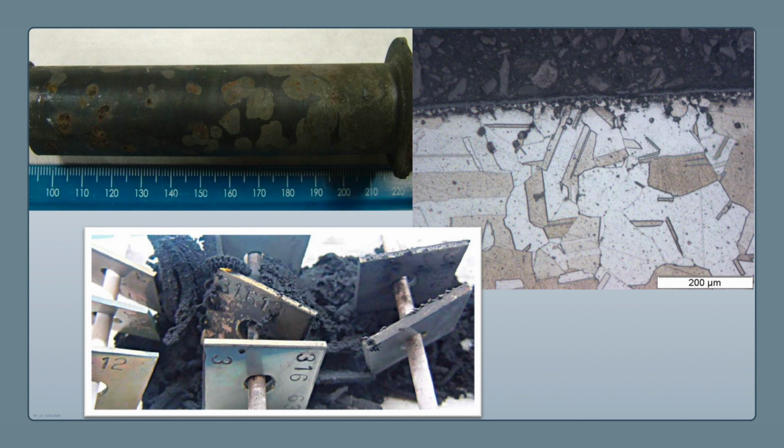In the bottom picture, we've done quite extensive work to try and simulate this type of failure or corrosion in the lab. Some of my colleagues have developed this furnace. We look at the environments and mix the gases and put them through the furnace, looking at different temperatures and time periods. These are also just 316 stainless steel coupons where you can see the dust that's come off. The coupons themselves still look fairly clean, so the dust isn't inherent. It falls off of the coupon. So visually, sometimes the steel still looks fine, even when the dust comes off, but obviously it's losing integrity.